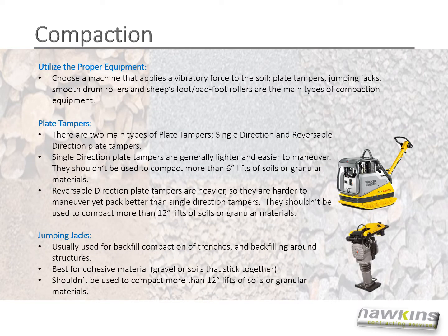Utilize the proper equipment. Choose a machine that applies a vibratory force to the soil. Plate tampers, jumping jacks, smooth drummed rollers, and sheep's foot, pad foot rollers are the main types of compaction equipment.